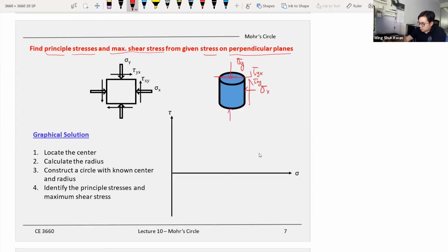So in reality, you get all the reaction forces. Now you apply all those stresses on the solid elements. You can do this in the lab, and also you can do it in the field. Examples in the field: we are loading the ground because of a structure, so this structure creates a loading on the solid elements. Also with consolidation you have horizontal stress, and with sloping ground you may also get shear stress. So you have all these stresses in the ground.